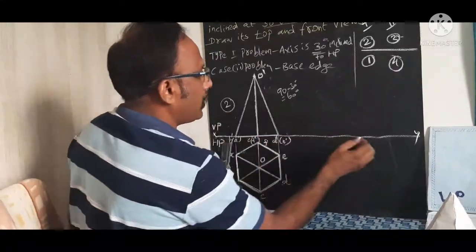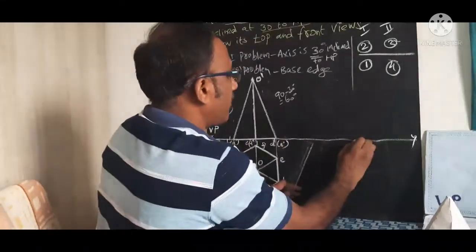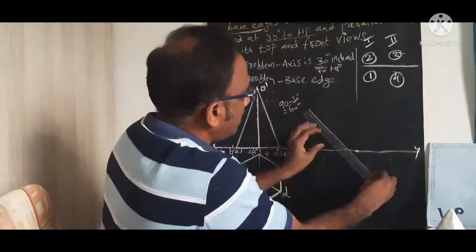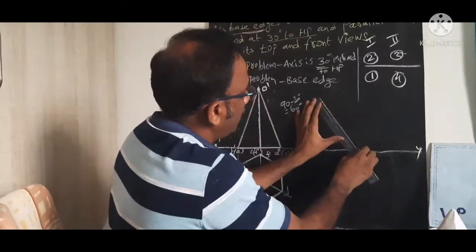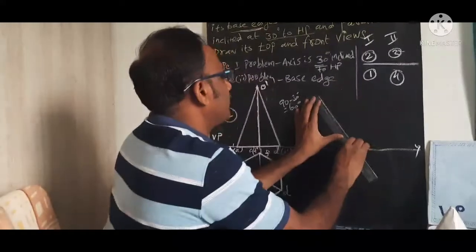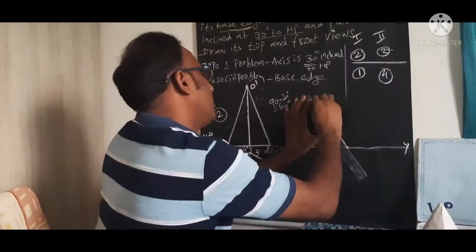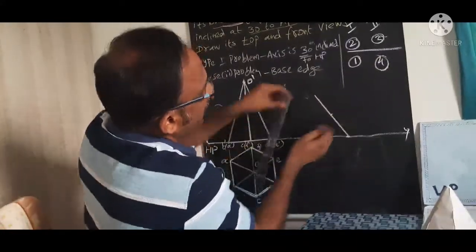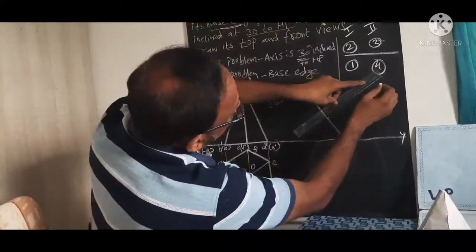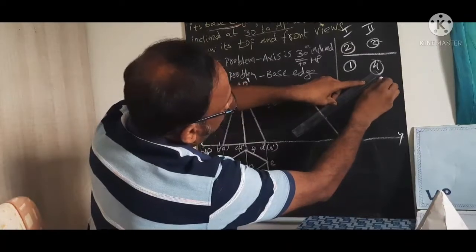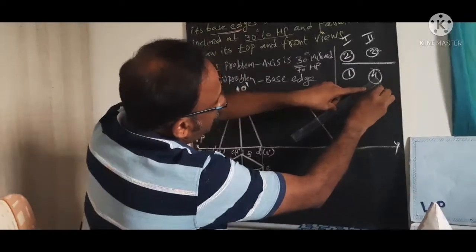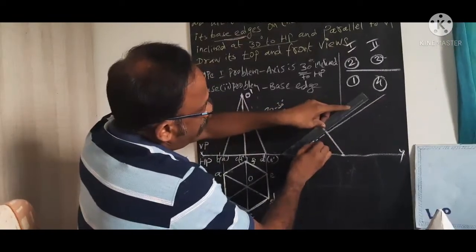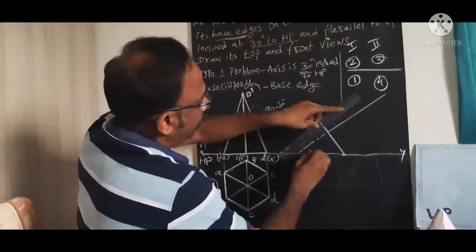Now I will take this point anywhere, right? From which we need to draw one 60 degree line. You need to draw one 60 degree line here, like this, for your height. Then you mark this point. Take this point, through which you need to draw this vertical line, right? You need to draw this. This is to be extended because it produces the axis line.